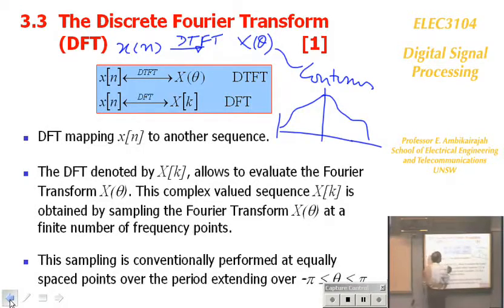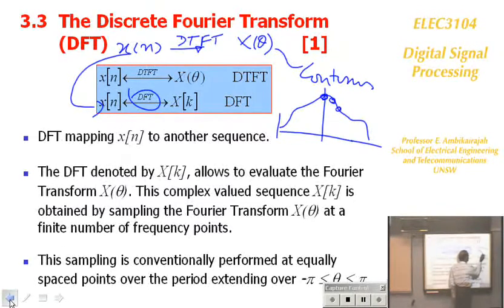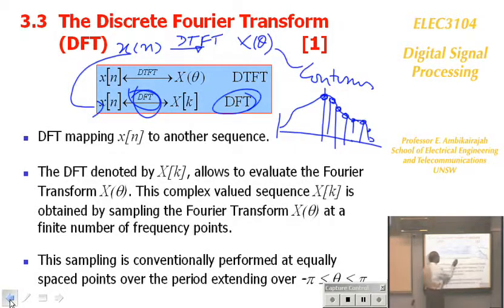But we don't need that. If you take the same signal and the signal only has certain frequencies, not every frequency, you use discrete Fourier transform, which will tell you which frequencies are present. It will tell you, here is a DC component available. It analyzes equal intervals. And if you use that, that's more than enough for any application. Not only that, you can implement them very fast on a computer using the FFT algorithm, the fast Fourier transform algorithm. FFT is not a transform. A lot of people think it's a transform. No, it's a fast algorithm.